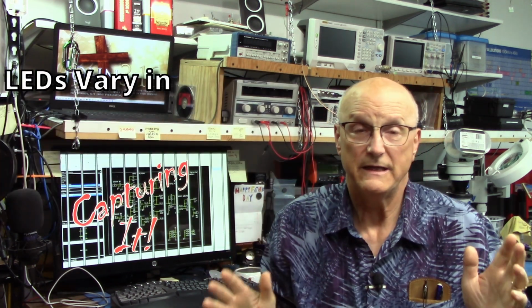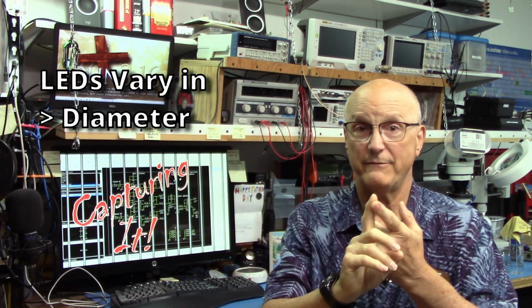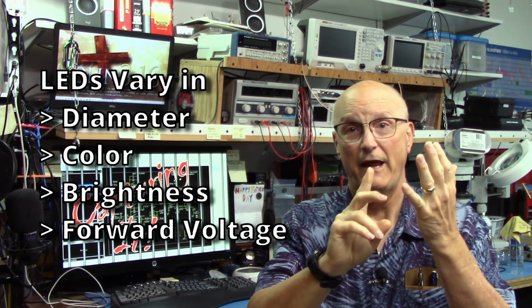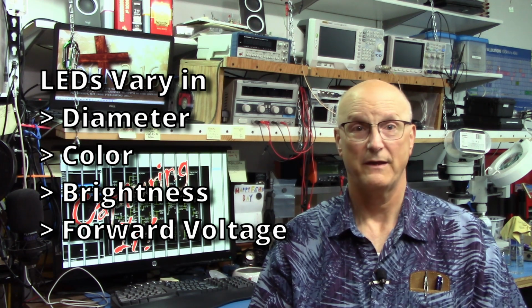Now, LEDs vary in physical diameter, color, brightness, and forward voltage rating. We have to keep all of this in mind when choosing the exact LEDs to specify in our bill of materials and calculating their current limiting resistor. We don't want the green LEDs looking way brighter than the red ones or vice versa. We want them to be all the same size and the same shape.